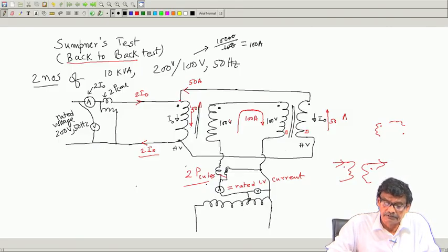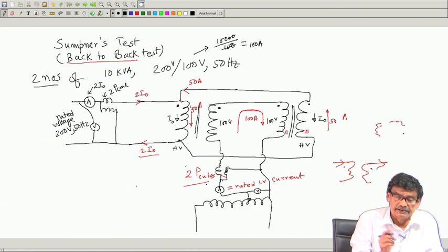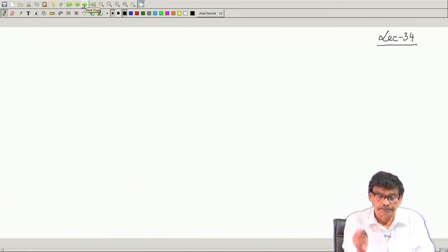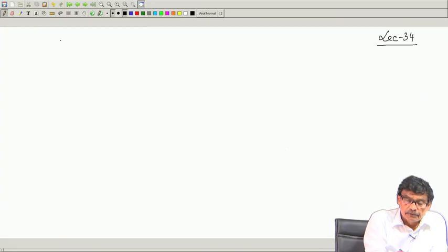And these parameter values will correspond to the rated temperature. For example, while carrying out the test, you energize the transformer for a long time, maybe hours, so that the steady state temperature is reached. But it is an interesting test. Now, today we will start three phase transformers.